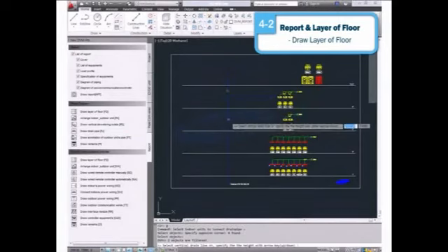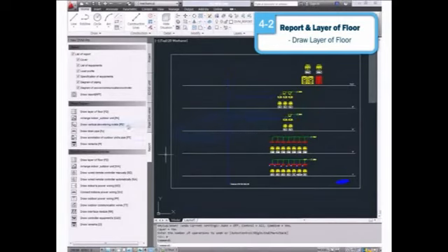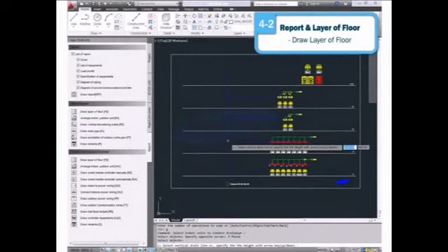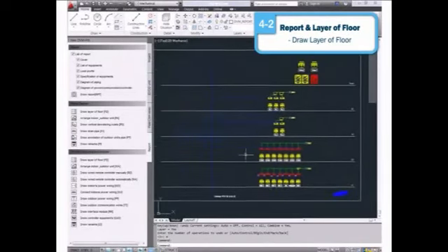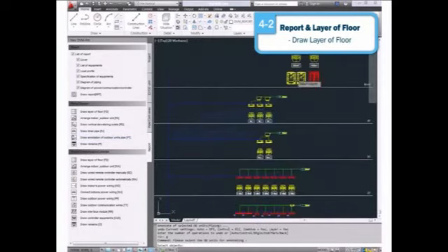When small square box type cursor appears, move it to the vertical piping, and click the mouse. You may press the up and down keys on the keyboard to adjust the height of the piping. For the floors with the watering outlets instead of the vertical piping, drain piping will be connected and displayed on the indoor unit of the schematic diagram.